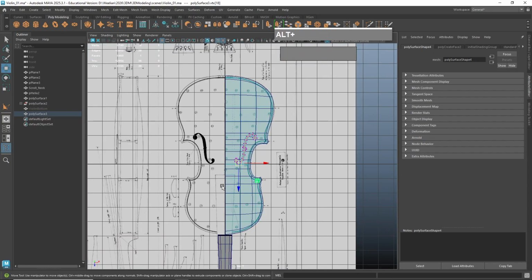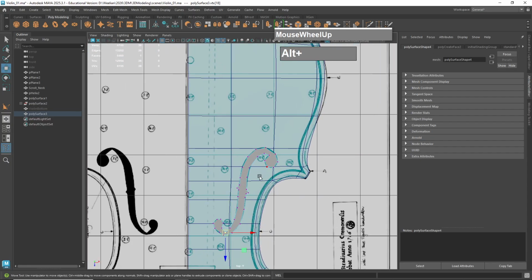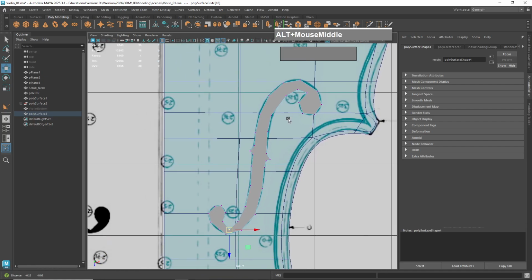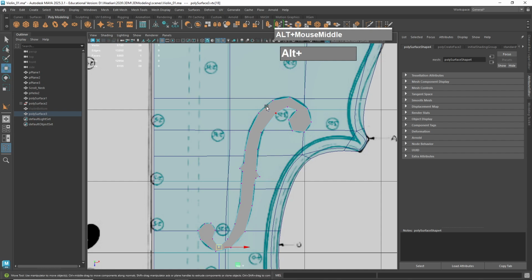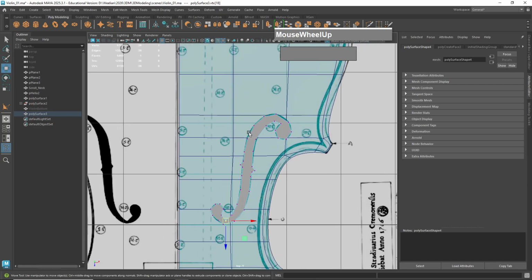So for this piece, right, I'm just going to extrude one long piece here. I'm going to be using the Boolean tool to just cut a hole here. Then after that, I will refine the topology here. So you can see there's a lot of lines here that I will have to go and reflow.